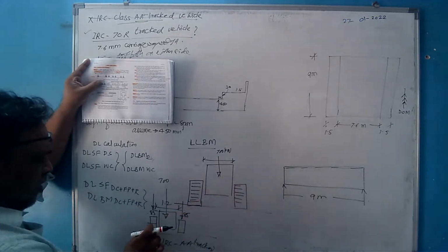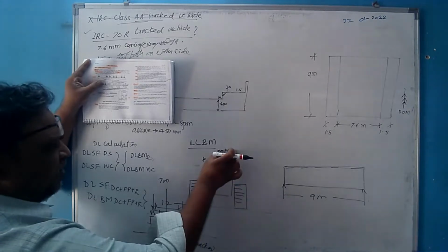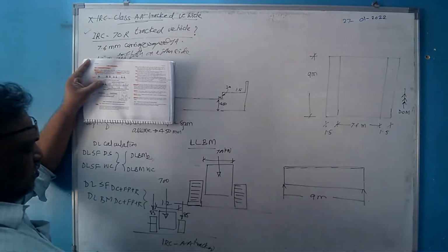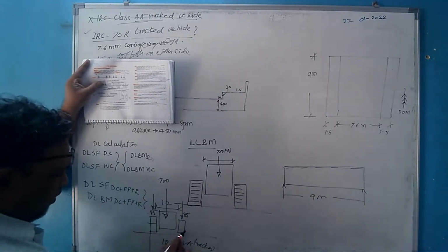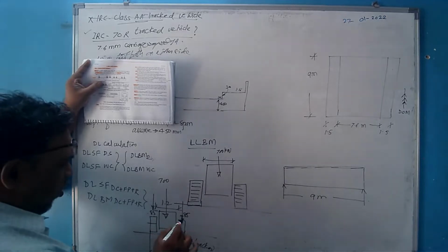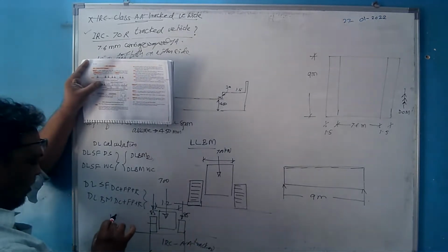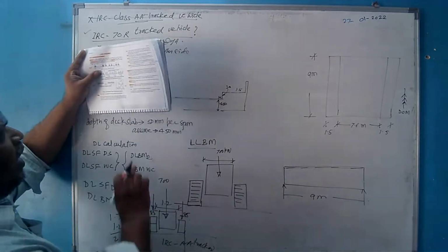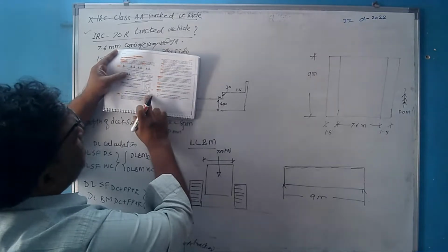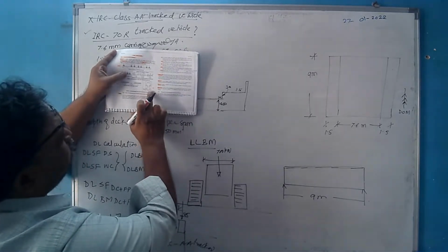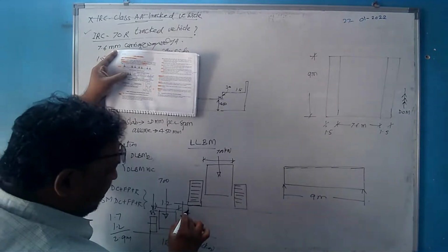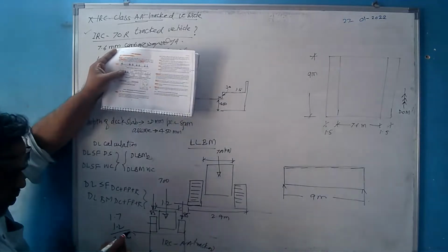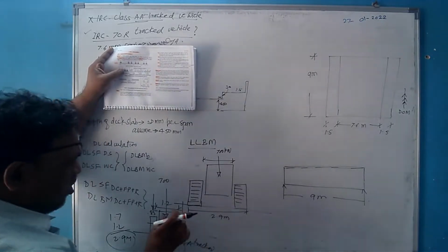It is the same: main body, two tracks. If it is 700, it will be shared by two tracks equally, 350 and 350 kilonewton. How much was this outer to outer of the wheels or the tracks? 0.85 plus 0.85 is 1.7, plus this 1.2, it was 2.9 meters. And what is given here? From outer to outer of the track, the total width is again 2.9 meters. Just as it was 2.9 here, it is 2.9 here too.